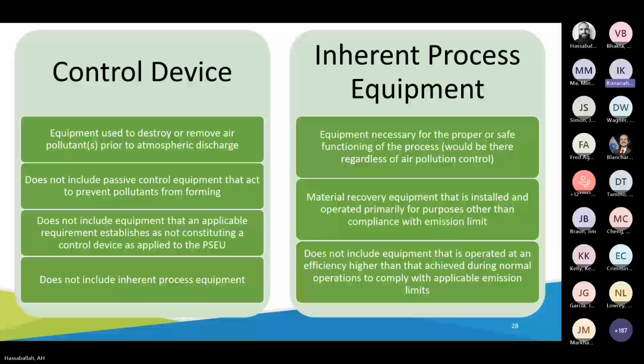They may have a baghouse or some other fabric dry filter control. Then the particles collected are reused in the powder coating process, and they have nothing else. In that case, I do not consider these control equipment, but they are part of the process. Do you agree with it?